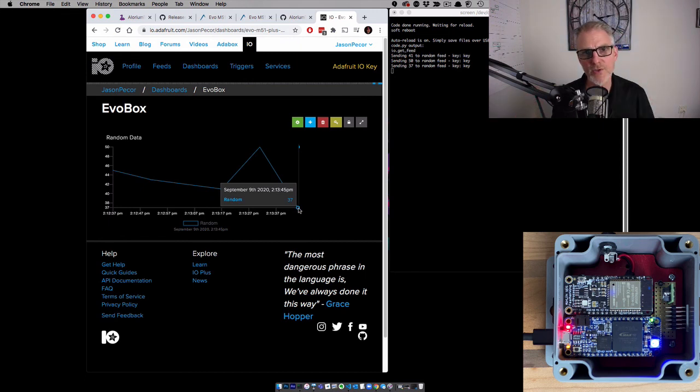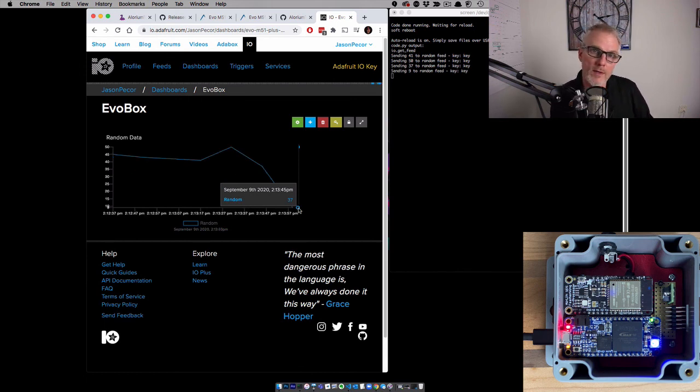Now, you certainly do not need an FPGA to generate random numbers and send them to an IoT dashboard. That's absurd. But the idea here is that one of the areas that you might want to use, and where our customers are indeed using our hardware, is for doing much more aggressive or much higher performance processing of sensor data, some kind of sensor fusion applications where high fidelity analog to digital reads are being done, brought into the FPGA where there's some DSP algorithms happening, and there's a lot of those happening in parallel, and then that data is what's getting pitched out of the board and either up to an IoT dashboard or as part of a host system in a larger compute environment. And so that's where using the FPGA starts to make sense.